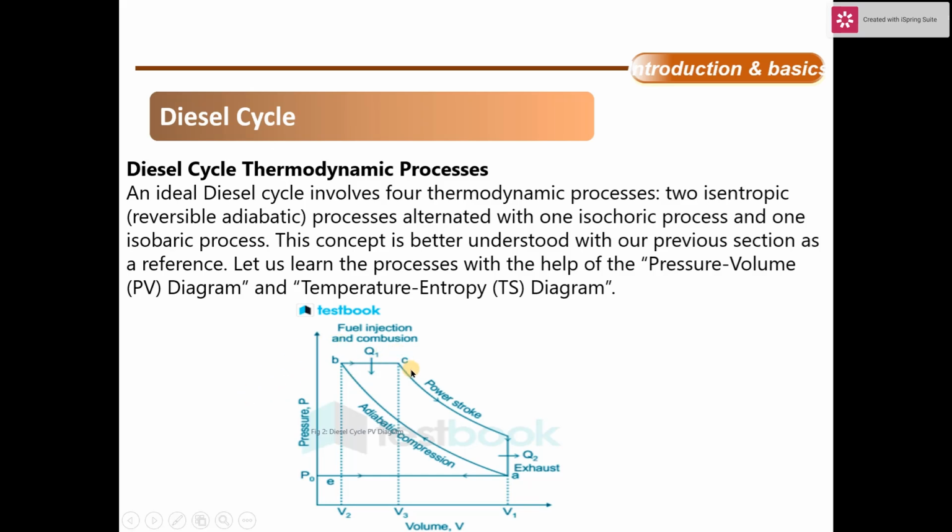This is expansion. Now, the combustion of fuel occurs towards the end of the compression process. The expansion pushes the piston to the bottom dead center. During this phase, the intake and exhaust valves are closed.